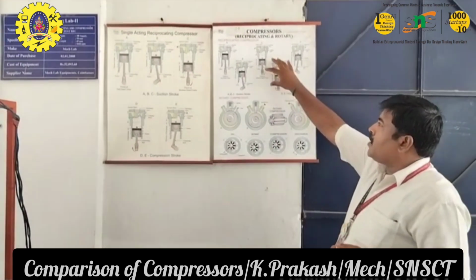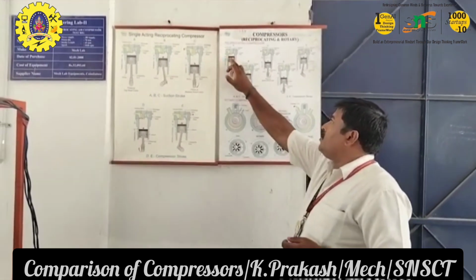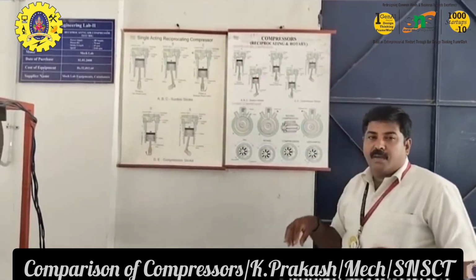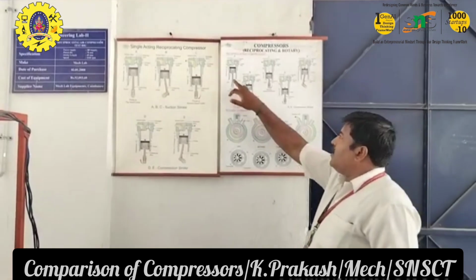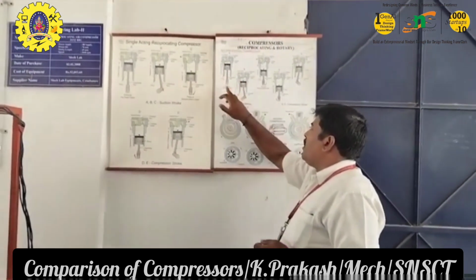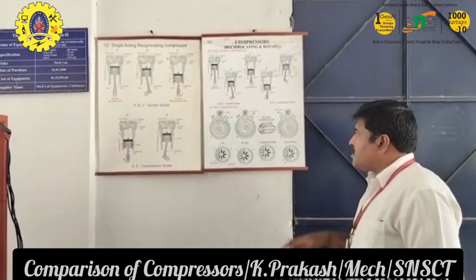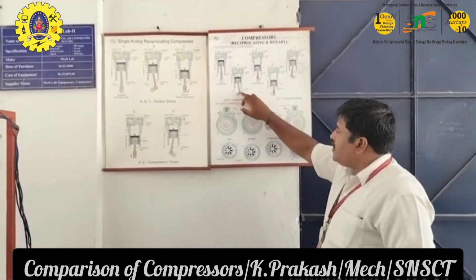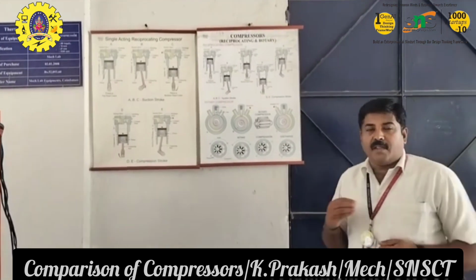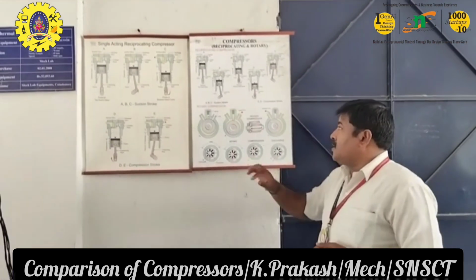If we see these reciprocating compressors, the components available are a suction valve, a discharge valve, and a head where the valves are arranged. And there is a piston, which is connected with the connecting rod and the crankshaft. The power for this crankshaft is given with the help of a motor, where the input is electrical energy. Through the belt drives it is converted into mechanical energy.